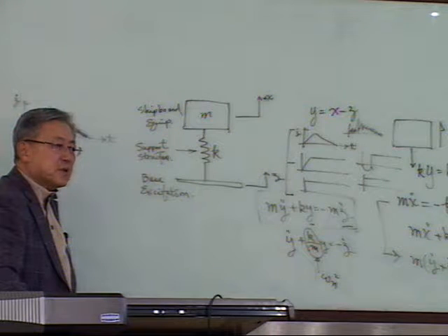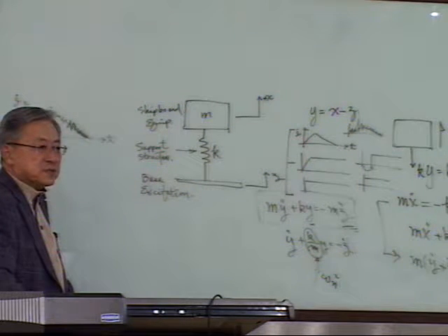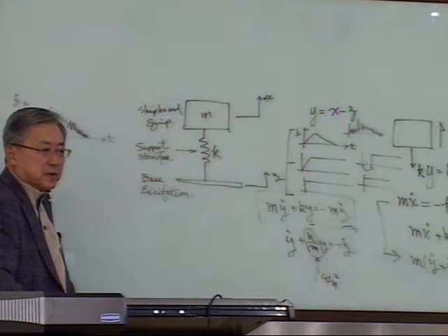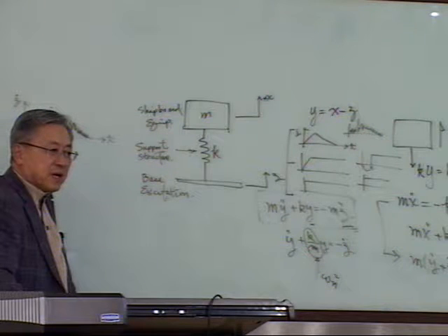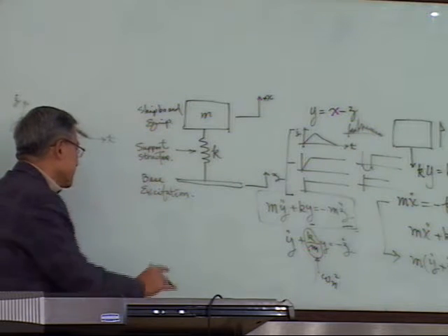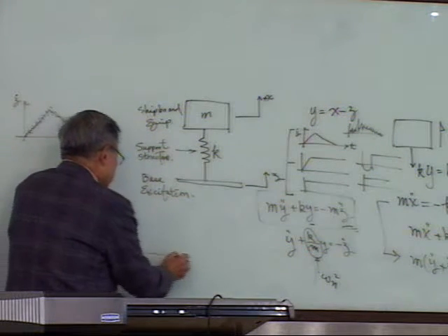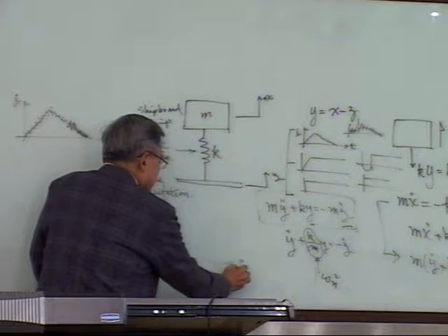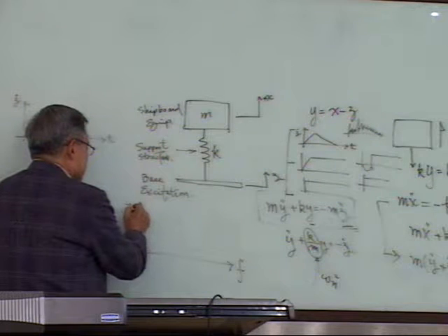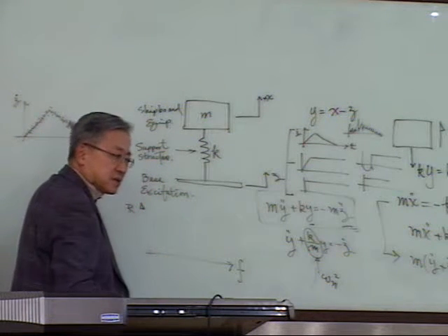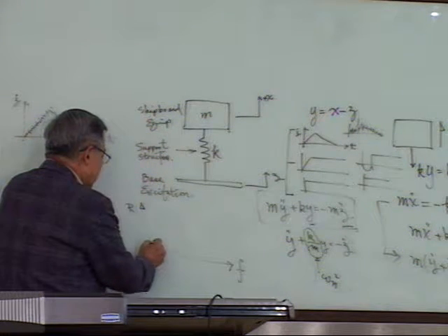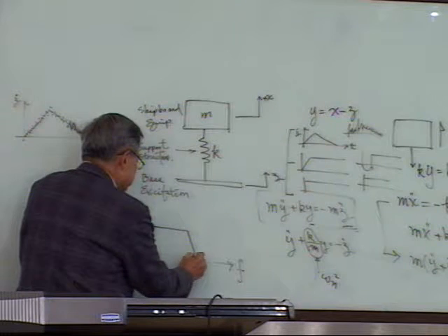So usually when you go out to conferences, a lot of the time the equipment builders come out to show so-called shock spectra, saying that, okay, this is a shock spectra, a frequency versus the response. Response could be acceleration mostly, okay? Then they show, this is our design spectra.